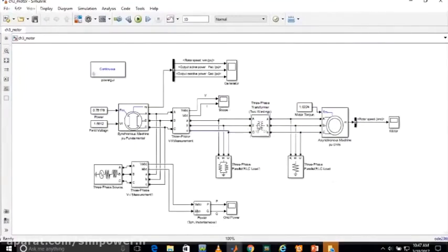In this we have connected a three-phase transformer with two windings and an asynchronous machine PU. Because now we have more than two systems, two generating units and one asynchronous machine, in order to initialize these three, we are going for load flow rather than machine initialization.